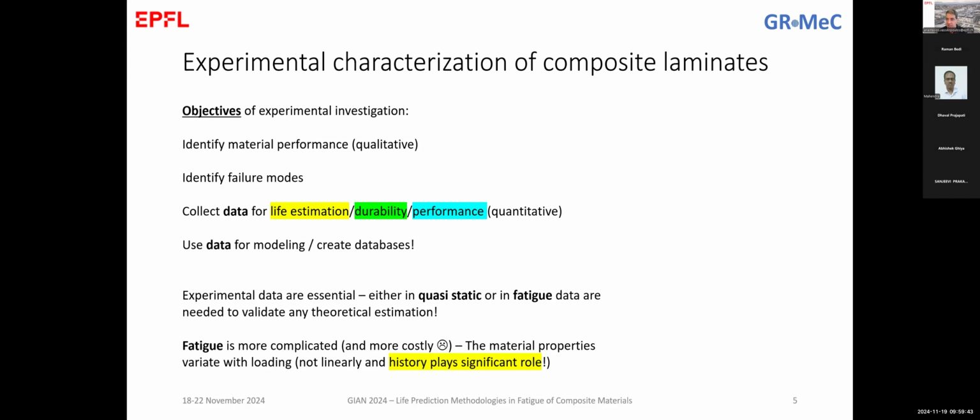And as you mentioned, these tests for wind turbine blades can take very, very long times, because there you try to simulate the actual frequency of wind, and usually this frequency is around 1 to 2 hertz, which means that to reach 1 million cycles you need at least 10 days, and to reach 5 million cycles, you might test the specimen for more than a month. The specimen in this case is a complete blade.